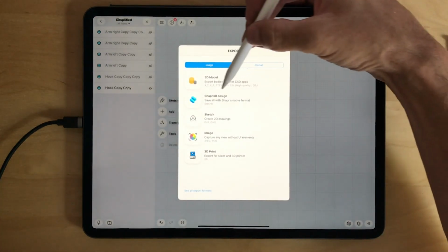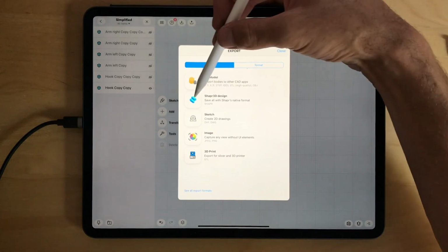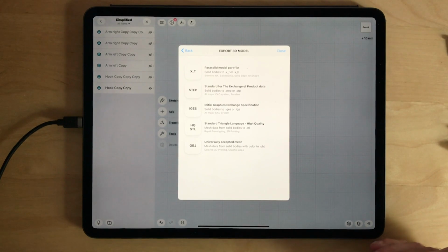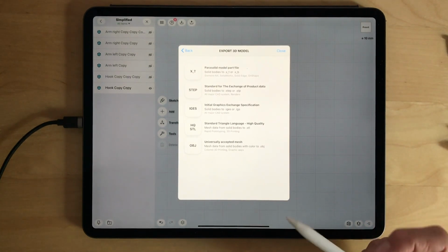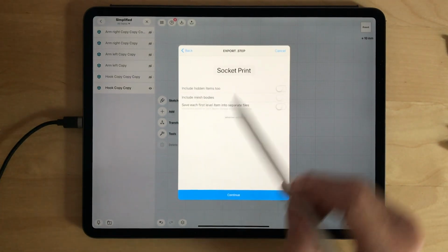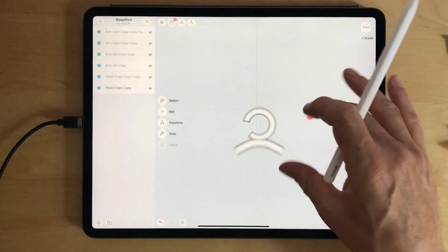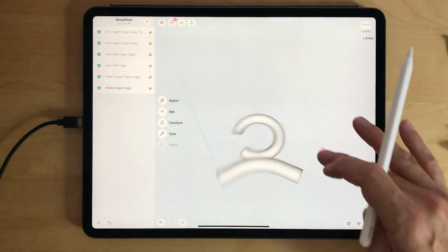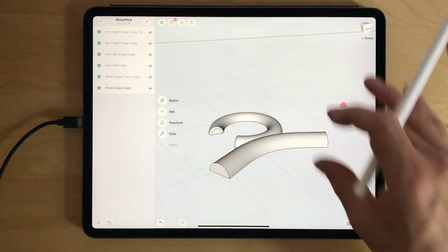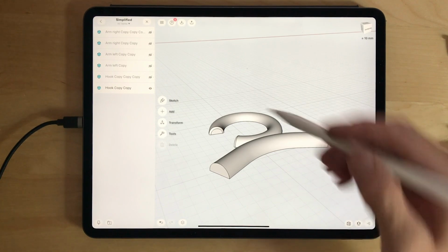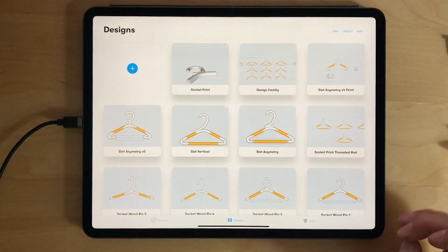Then you can go to these websites and get a quote. And once you get a quote and you want to go ahead and make a small batch production, now you would export this as STEP. STEP basically is just the name for a CAD file, and essentially it will be this model, for example, just in a different format. That is very important in case a manufacturer might, for example, have to adjust the design a little bit.